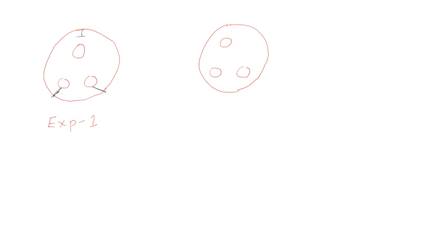So what I am left with is a capacitance here, this is CS, and one capacitance, this is CC, and another capacitance, that is CC. We won't get the capacitance between these two cores because these two are at the same potential, that is our sheath.